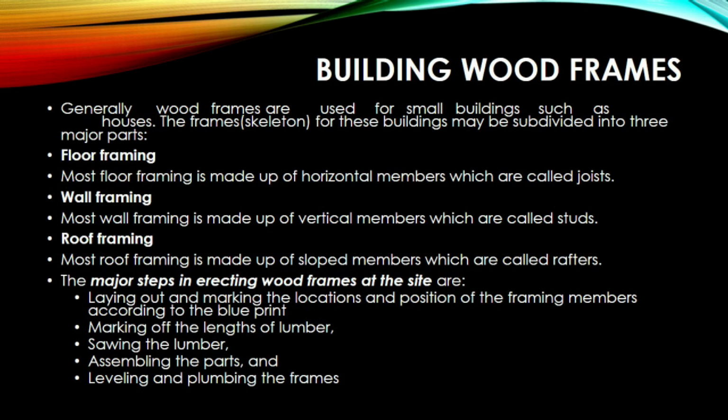The major steps in erecting wood frames at the site are laying out and marking the locations and positions of the framing members according to the blueprint, marking the lengths of the lumber, sawing the lumber, assembling the parts, and lastly, leveling and plumbing the frames.